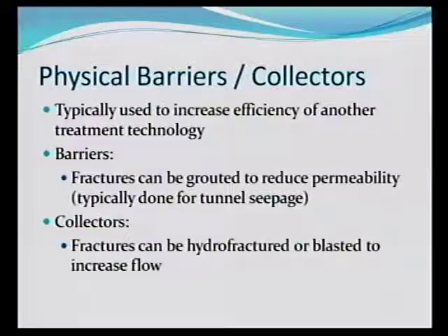in unconsolidated material. You can put in sheet piling walls. You can put in what are known as funnel and gate systems where you channel all the water to one place. You can put in permeable reactive barriers, which are basically trenches filled with reactive material so as the water flows through it, it gets cleaned up. There's lots of cool things you can do when you can dig a trench or when you can pound a sheet pile down into the sediment. We don't have that luxury in bedrock.